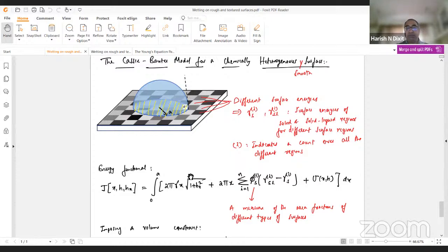Okay, so if you zoom in microscopically, if you're able to basically measure the angle where the contact line meets each surface, there locally the angle will be slightly different. You understand? There will be a little adjustment of the surface. For example, if the interface meets one of the light gray surfaces, the local angle is slightly different from when the interface meets one of the dark gray surfaces. The local angle, the equilibrium angle, or the Young's angle is slightly different at each location. From that, an effective angle emerges.